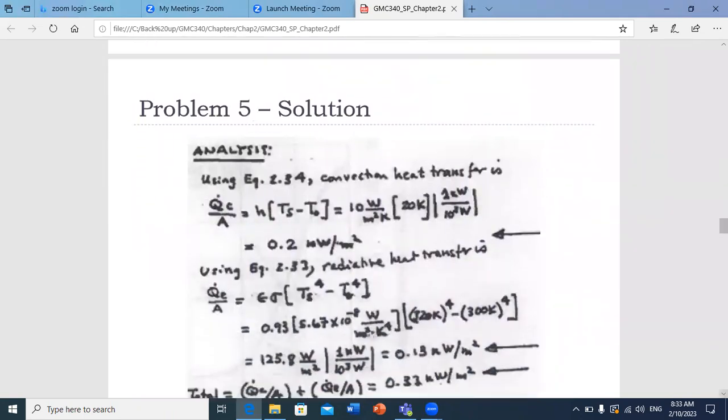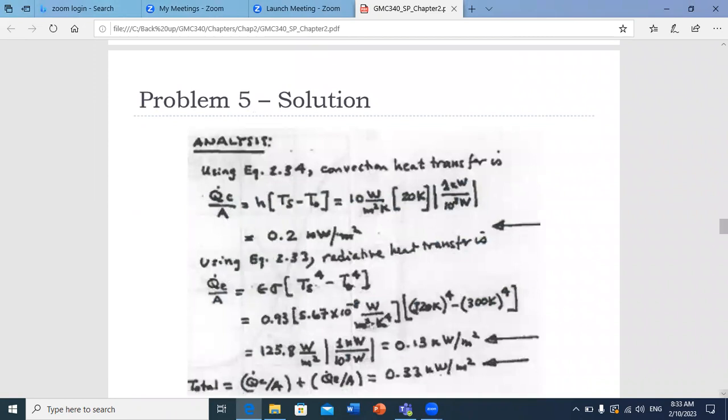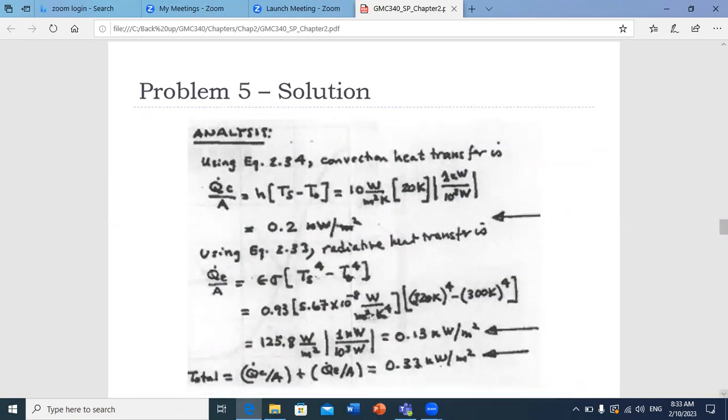Here, if you want, they should be more specific. They should tell you that the walls, or this enclosure, have a surface temperature equal to the air. Then you can do minus T0 to the power 4 as I did here. So the given should be clearer, to tell you that you are in a room, let's say, and they just give you T0.